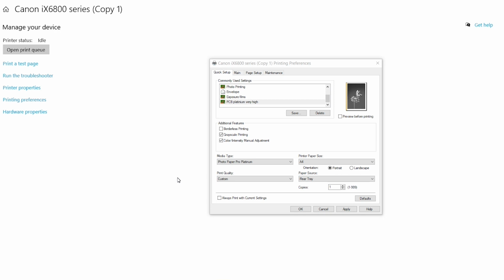And it may happen that you want to put in a film as many artworks as possible and go with tight margins, and this borderless printing will happen automatically, and you'll be shocked that there is nothing about the tolerance anymore. You measure it and there is a couple of millimeters error. No, it's not a couple of millimeters error. The printer is perfect, but you should not use this borderless printing.